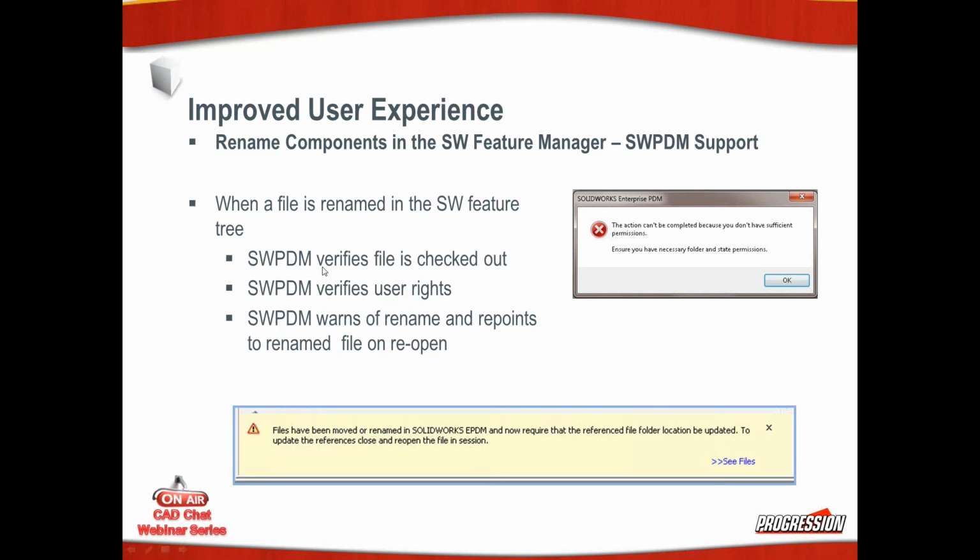And what will happen is it will verify, first of all, that the file you're trying to rename is checked out to you, and whether you have proper rights to do so, and then it has that warning about renaming, and it'll repoint and update the reference once it's been reopened. So again, the main goal here is making sure that all the references are maintained properly should we be renaming any files, be it in the EPDM Explorer interface or through the SOLIDWORKS interfaces. Okay, so a really nice improvement.